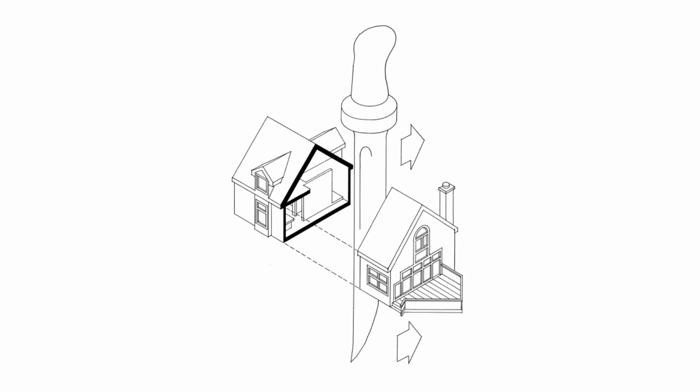If we were to slice through the house vertically, like slicing a loaf of bread, then it is called a section. Sections can be taken through any part of the building or object that would help to explain how it works as a building or an object. Sections can also reveal the relationships between the different parts of a building that might not be apparent in any other elevation or plan drawing.